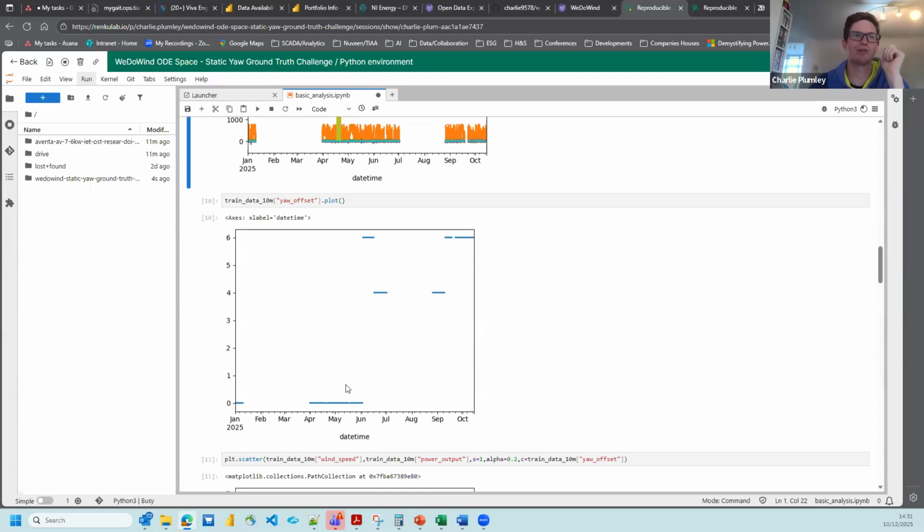And what we want to be able to do is predict these values or these changes, because then on a turbine where we don't know these offsets, we can identify them and so correct for them. So then the problem is that on the SCADA data, you observe 0, but actually the offset is maybe 2 or 3, and you just don't know yet. Yep, yeah, that's it.